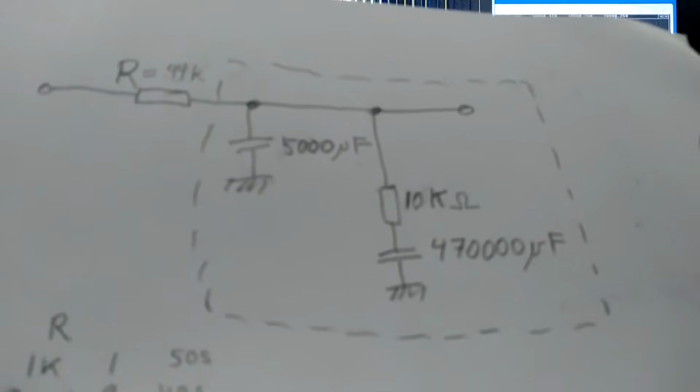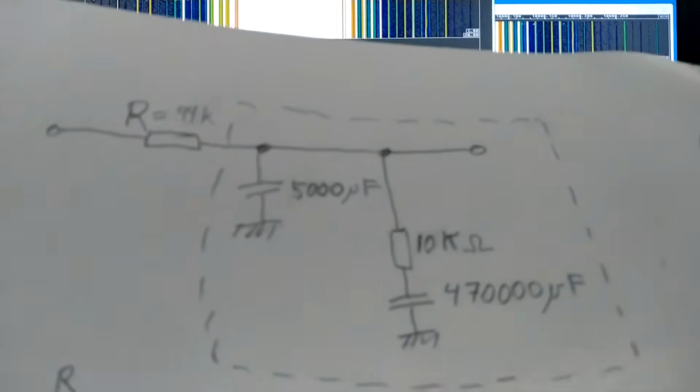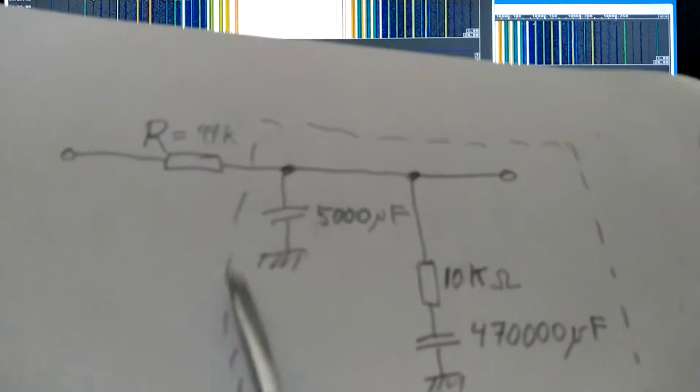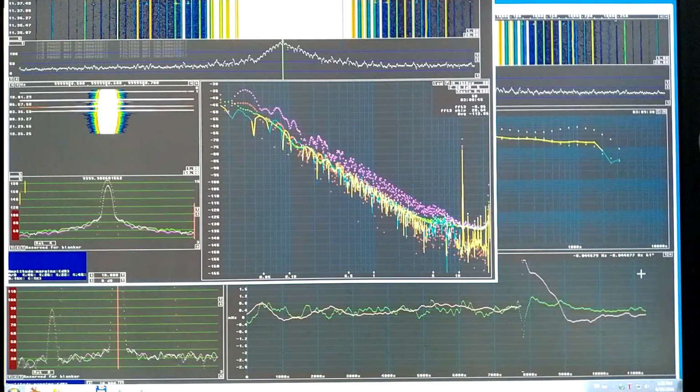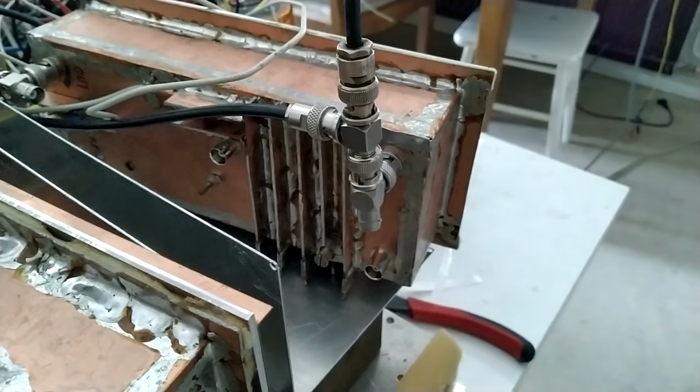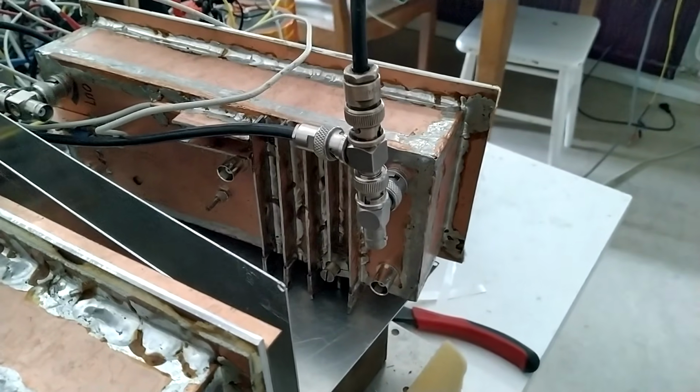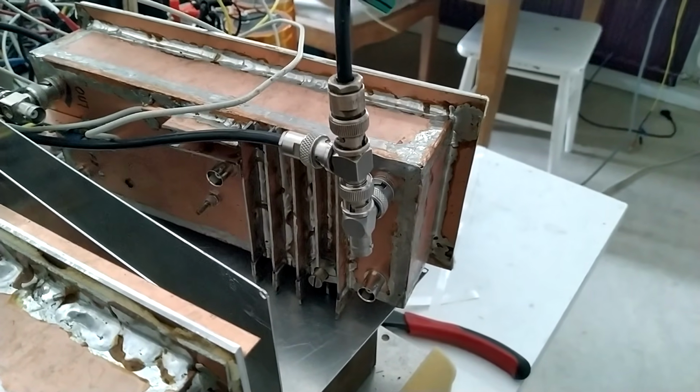I have swapped the loop filters between the channels, these components, but the result is not what I expected. I had thought maybe there was a noisy capacitor, but no, there is something else. There seems to be a noisy thermoelectric voltage somewhere in the connectors. This is the arrangement, BNC connectors.